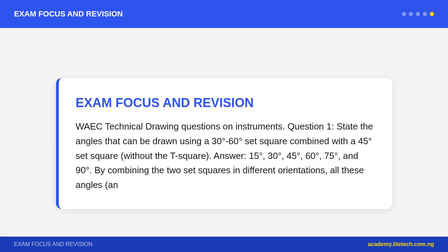Question 3. What pencil grade would you use for A. construction lines, B. visible outlines? Answer: A. 2H or H, hard lead gives thin, light lines suitable for construction work that will be erased. B. HB or H, medium weight gives clear, visible outlines that will be retained in the final drawing.